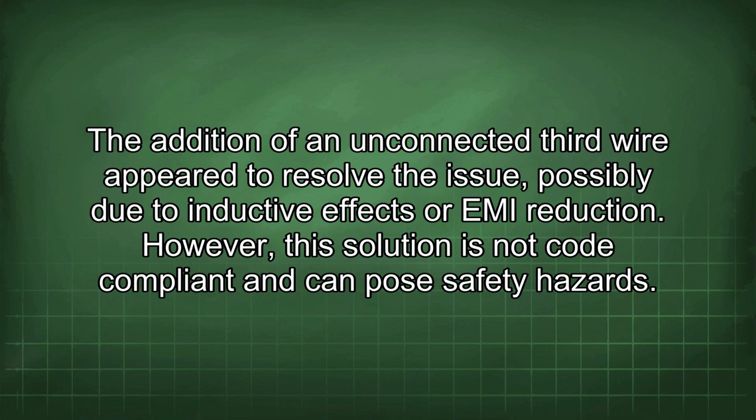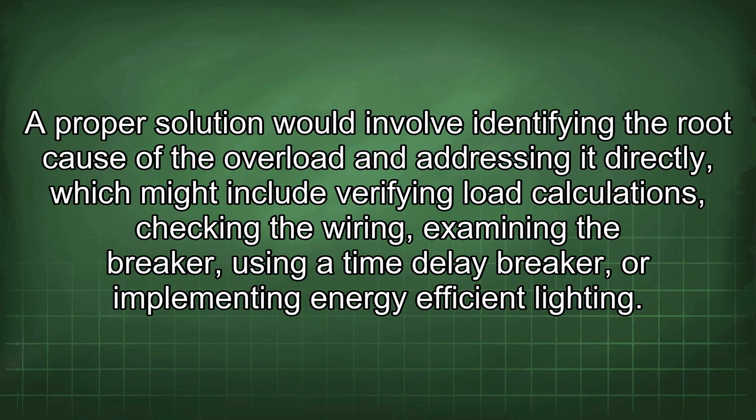The addition of an unconnected third wire appeared to resolve the issue, possibly due to inductive effects or EMI reduction. However, this solution is not code compliant and can pose safety hazards. A proper solution would involve identifying the root cause of the overload and addressing it directly, which might include verifying load calculations, checking the wiring, examining the breaker, using a time delay breaker, or implementing energy-efficient lighting.